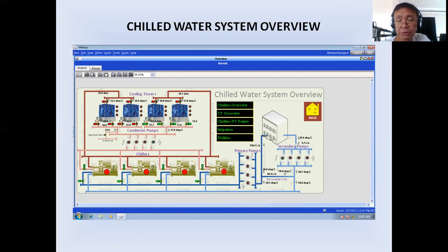They will deliver their own DDC, and they have an engineer who will program the operation of this water cooled chiller. Because as you see, the system is a little bit complicated, so they have developed a control logic program for this specific application. But if you're a BMS engineer and there are only two chillers and several pumps, primary and secondary, it will be easy to do the programming because it is not so complicated.